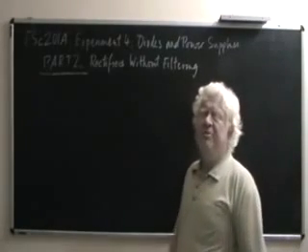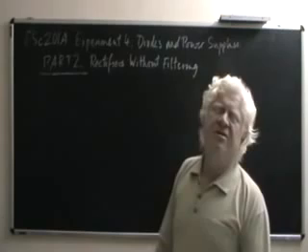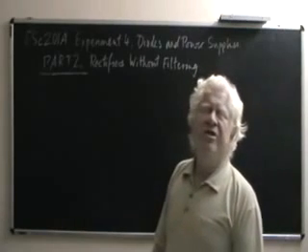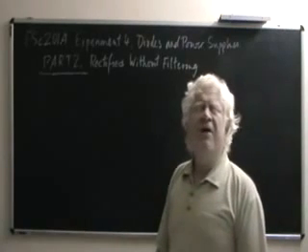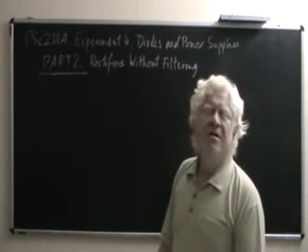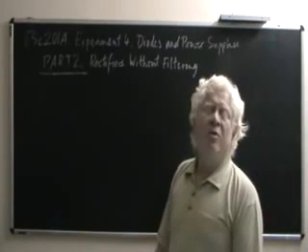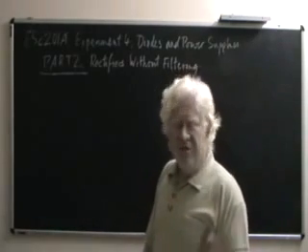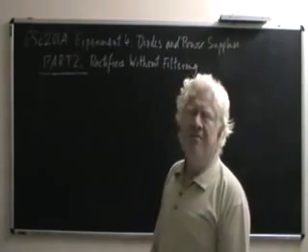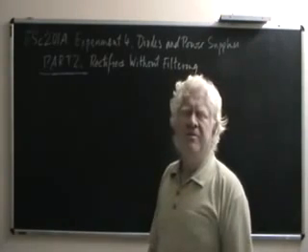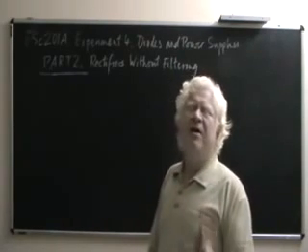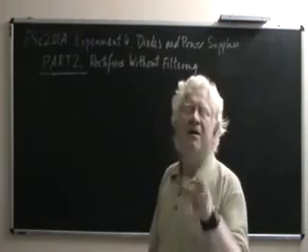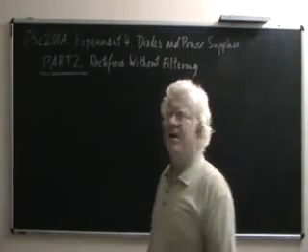The second part of the experiment consists of building a rectifier. What is a rectifier? A rectifier is a circuit that converts alternating voltages, that is voltages which go both positive and negative with respect to the other terminal, into a voltage which always has the same polarity, though not necessarily the same magnitude. Let's take an example.